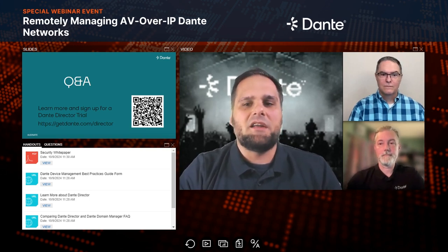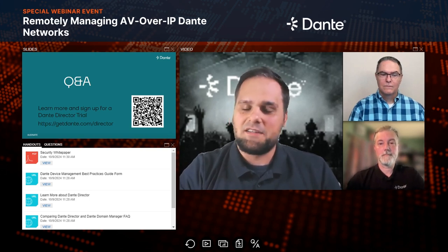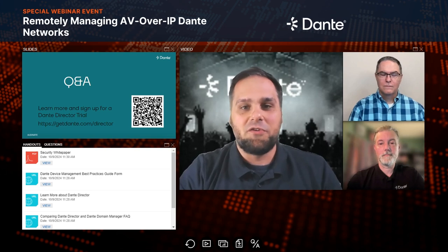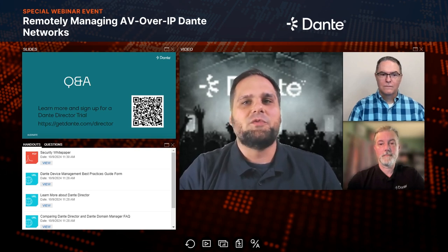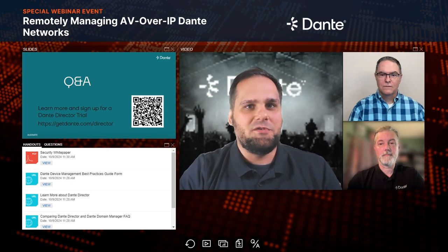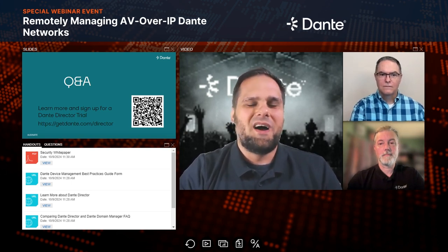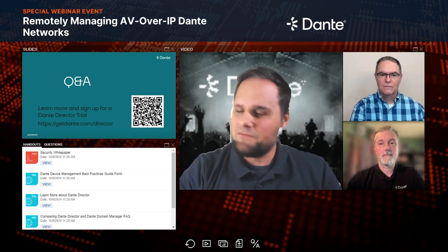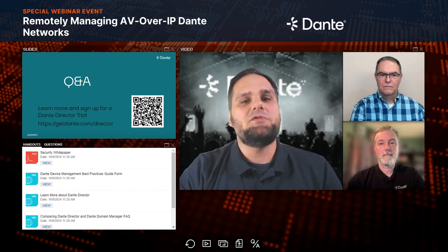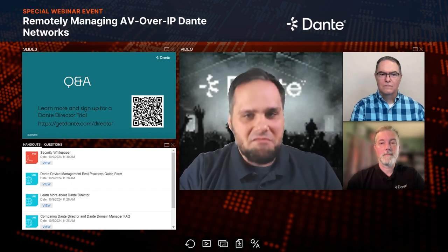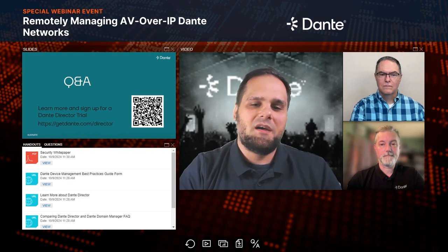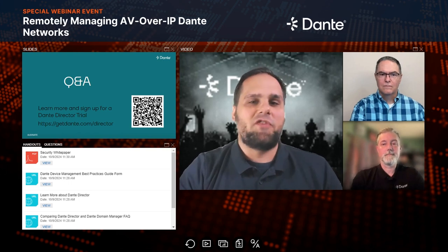But I would just add, when you're looking at switch selection, the one thing that we absolutely will break Dante is if you have what's called energy efficient Ethernet, also known as green Ethernet, where the switch will try to power off ports when they're not being used. That can really mess with some of the Dante clocking and timing settings. So anything other than a switch that has green Ethernet enabled will work with Dante. But as you get into more complex managed switches, that will give you more of an ability to create VLANs, to set up profiles per port, do all of those network management things that you'd like to do.